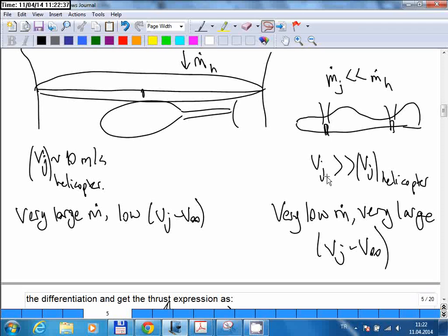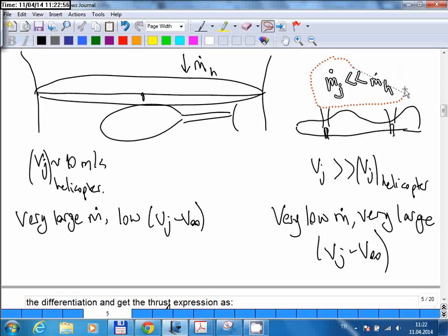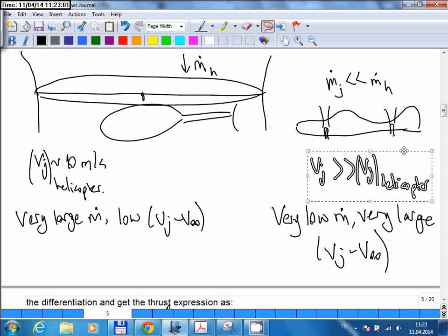Okay, so with a Harrier, you can create a vertical force equal to the weight of the aircraft, but if you look at how efficient that engine is, it's very, very low compared to a helicopter, because you have very little mass flow and a very large acceleration. Because of that, helicopters are ideal for hovering.